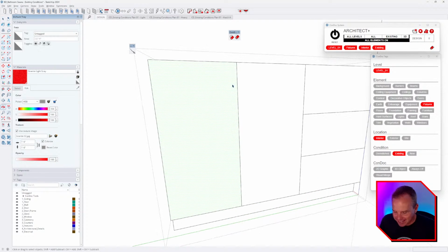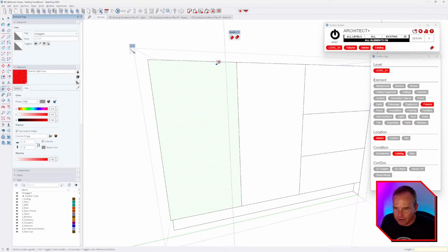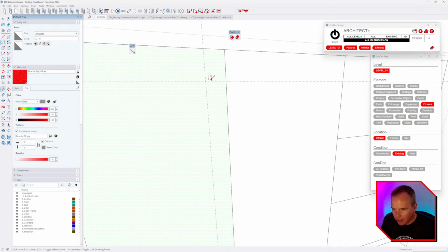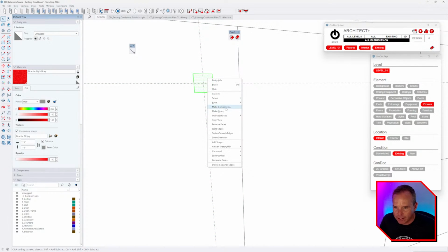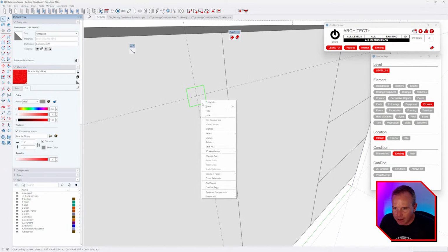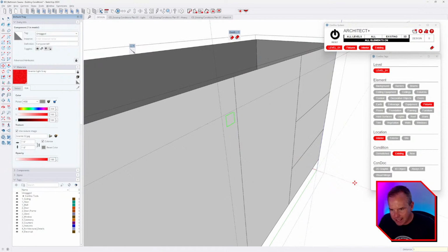Maybe you'll do it. To create those poles that we have going on, I'm just going to offset by like 1.5 inches, maybe 2 inches, and then make them like 1.5 inches or so. So I'll make one here, 2 inches. Then we'll come down maybe 3 inches. I'm going to draw a square and tap Control to go about the center. And I'll type 1, and then double click, make it a component. And then I believe I have to unglue that. And then click and move it on the red. And we want to move it out here by say 1 inch.